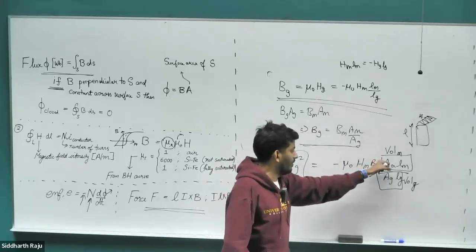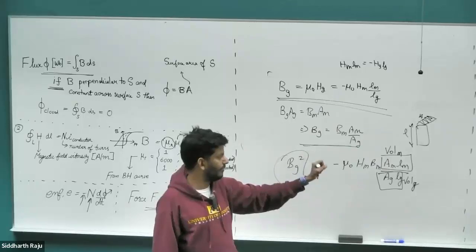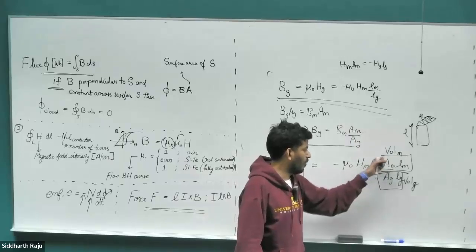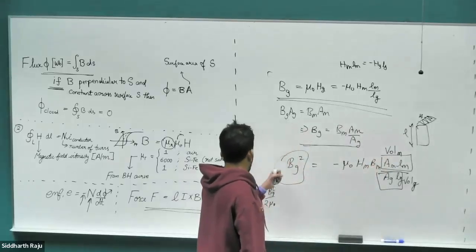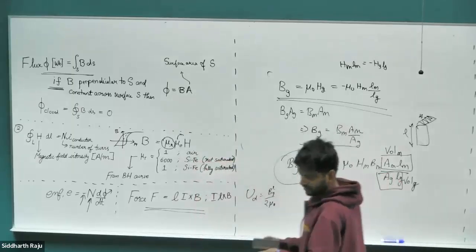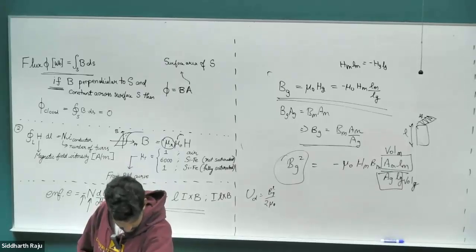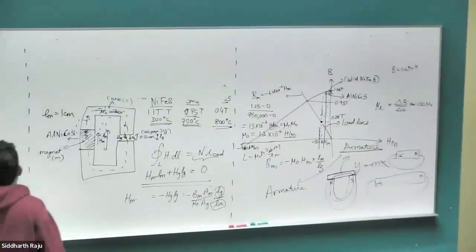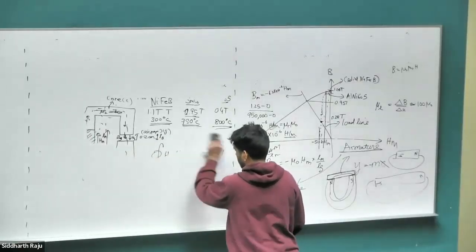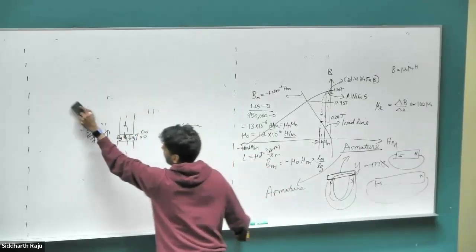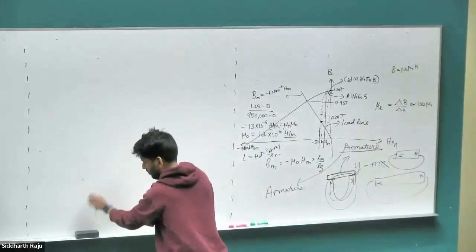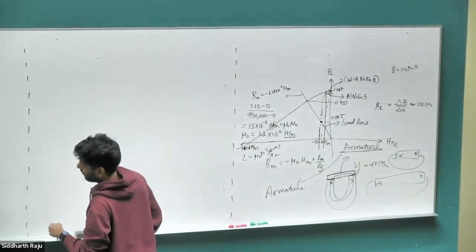So the volume, we want to minimize as much as possible the weight of the material we're using for our magnets, particularly when it comes to neodymium. So we want to limit this volume that we have, AM times Lm, while we want to maximize our Bg value, right? So what can we do?